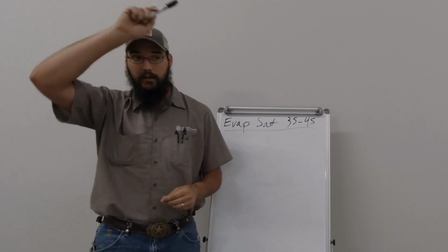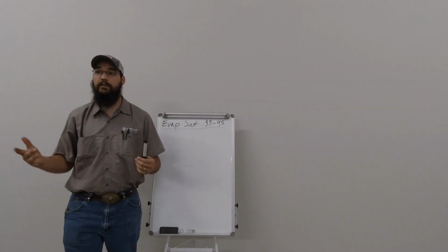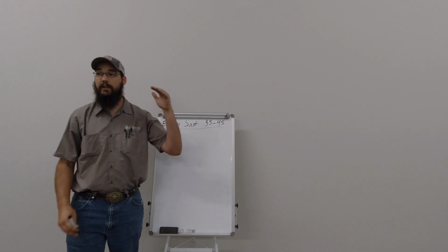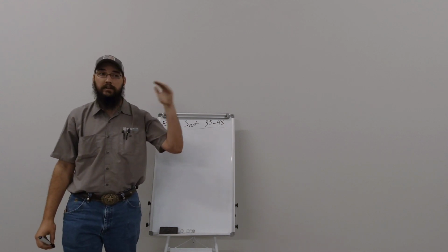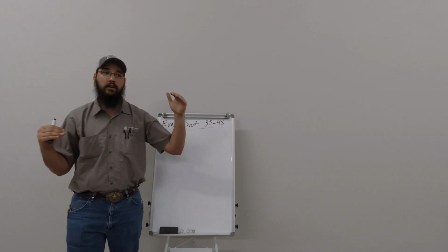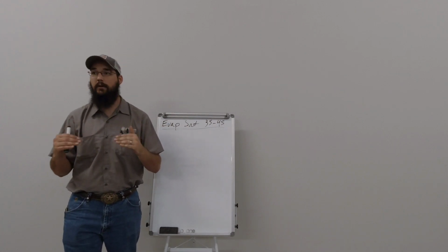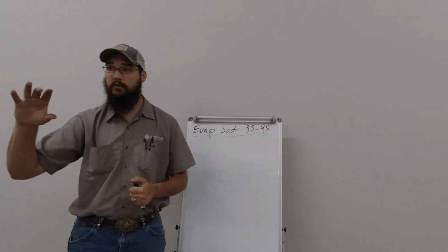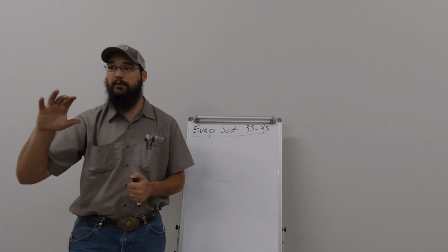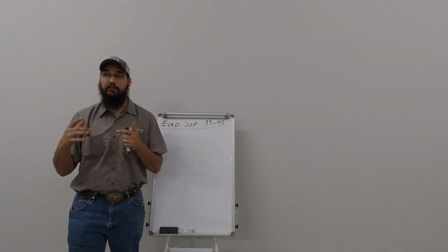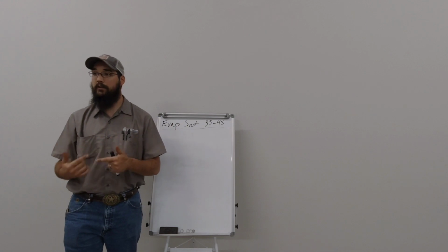We will pause there. Glide, refrigerant glide. 407C is probably one of the most common ones we run into today. There's a different saturation scale in the condenser than there is in the evaporator. You can't use the same scale for both. You will screw it up. It sounds kind of backwards. In the condenser, you use your bubble chart on the temperature, and in the evaporator, you're using your dew chart. We have to remember those things, because we will get in trouble.